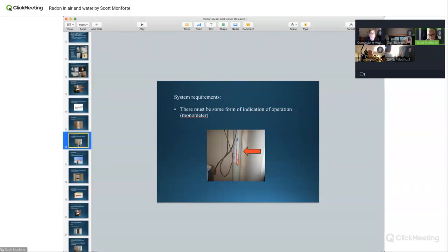The manometer. I get people all the time to look at it and say, my radon level is good. It's 2. And I say, well, the manometer has nothing to do with radon levels. People think, oh, but radon's great, it's been running a 2. All that tells me is that it's just a device to let the homeowner know it's working.